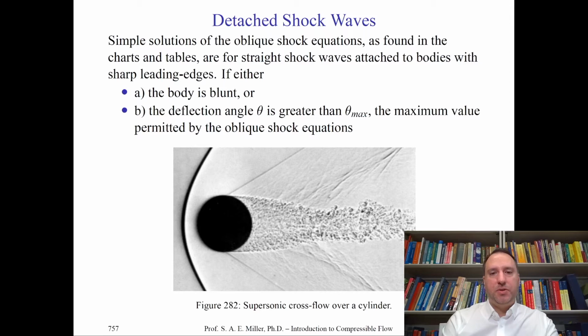Here's another simple Schlieren, but this time it's a cylinder in a wind tunnel, and the flow moves from left to right instead of the projectile or object in the fluid moving from right to left. Once again, we see almost the same type of flow physics. We see a bow shock, some transition to supersonic flow, which is much cleaner than the previous case.